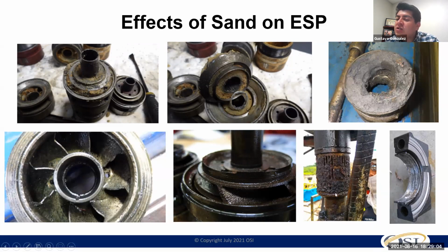Another thing is plugging at the intake. ESPs, by default, come with a screen as an intake. If you do the calculation of how much fluid you're actually flowing through, in some cases the best approach, due to the high delta P that you're generating over this intake, is to remove this small screen section that is 1 foot long. You can cut that out and remove it. You can ask your ESP supplier. At that point, you will expose 3 different holes, and you would increase the open area.